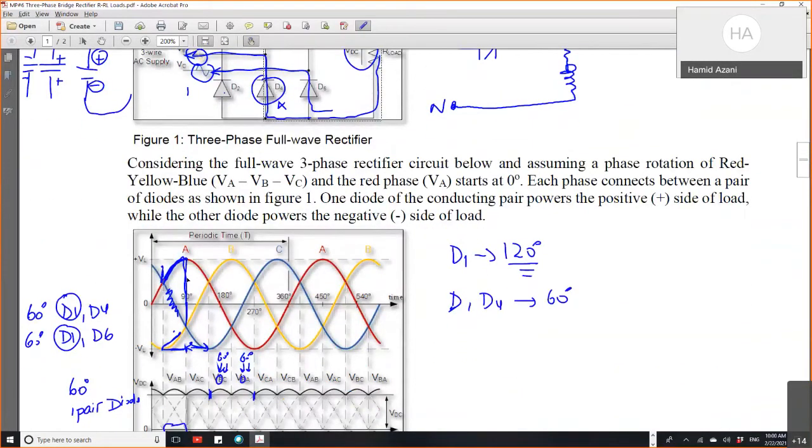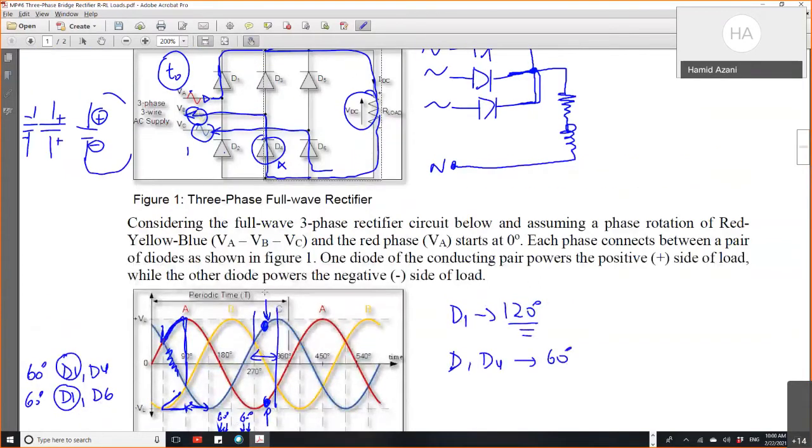And you have the three-phase system in front of you. You can easily identify one by one. Okay, so each 60 degrees, we have a pair of diodes, one here and one here. The one connected to C and the one connected to B, for example, for this case, to A, sorry. So C, which is D5.